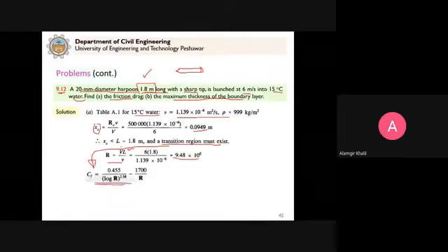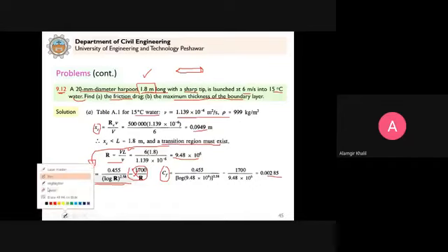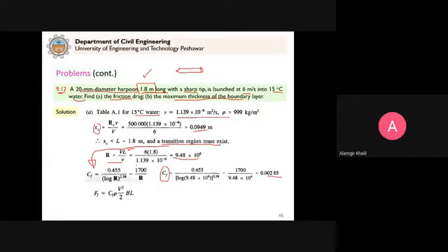This is what we studied for transition. We calculate the friction coefficient. Even if you use the Reynolds number and you skip this one, you will still get a value very close to this one. So if you use the turbulent flow equation, approximately you will get a very close answer. But if you want to be very accurate, then you can use this concept. And then FF will be equal to this equation, but this is the characteristic area here. Since we do not have a flat plate, instead of BL, we write A, the characteristic area A.